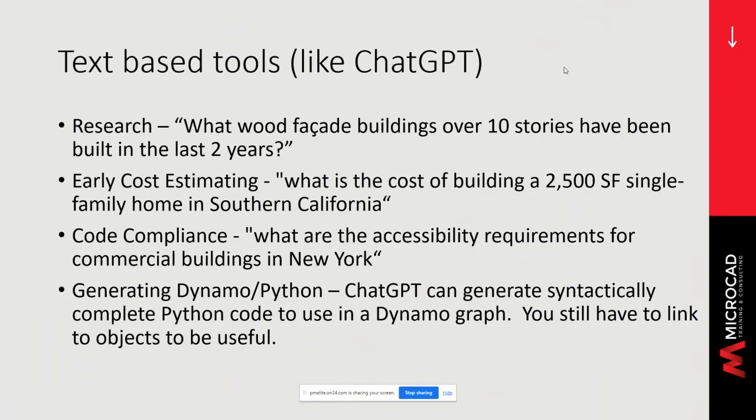Then ChatGPT would create Python code to find all of the doors adjacent to stair towers, find the property that is the fire rating, and make the changes necessary. This kind of usage requires a human to convert the Python code to reference real Revit objects, but it still could be faster than writing the code yourself because you just plug the Python code into a Dynamo script.